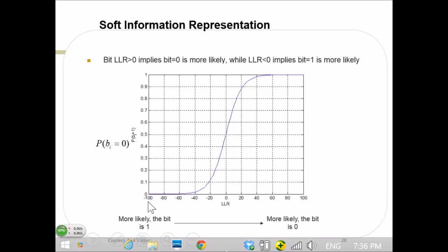You could choose to represent these values from -100 to 100, or we could choose to represent them from -15 to 15. If you do -16 to +15 or -15 to 15, you need fewer bits. That again comes as part of the fixed-point optimization, how many bits you need for the decoder.